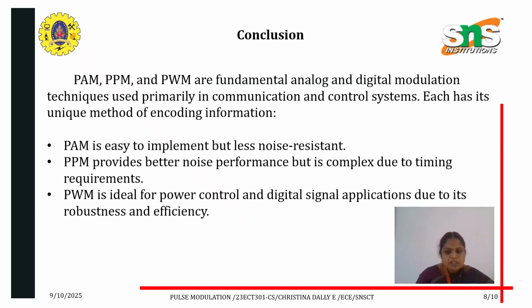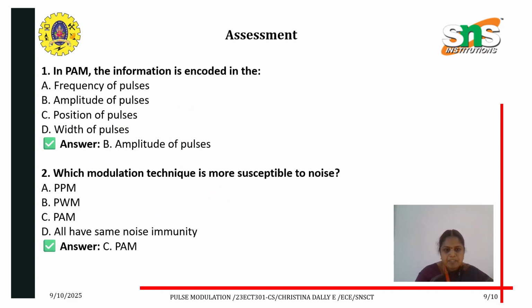Coming to the conclusion, PAM, PWM, and PPM are fundamental analog and digital modulation techniques used primarily in communication and control systems. Each has its unique method. PAM is easy to implement, PPM provides better noise performance, and PWM is ideal for power control and digital signal applications.